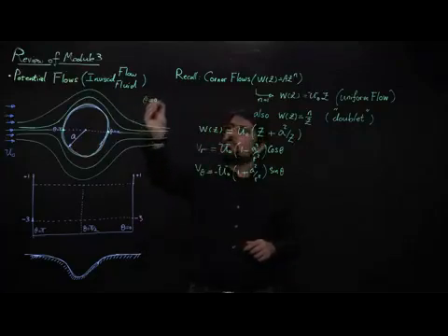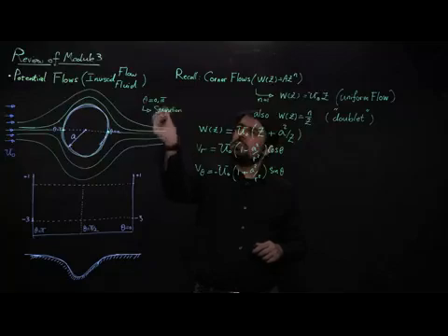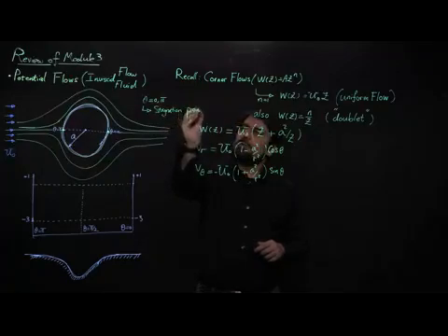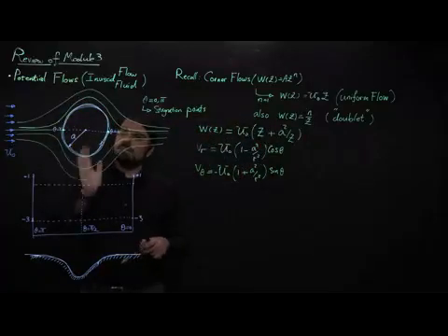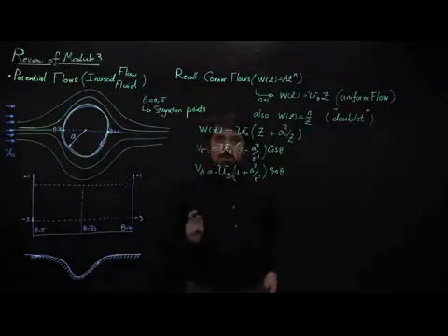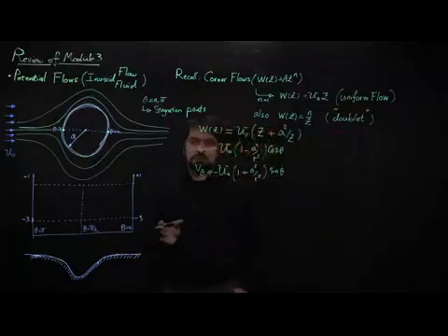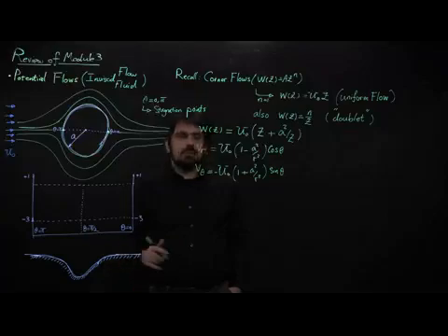So theta equal to 0 or pi are the two stagnation points that we have in this flow, and they are sitting in the front and back of the object in a symmetric manner. The flow has a symmetry from top to bottom, and it also has symmetry from front to back. And in all these potential flow problems, once we find the correct combination of complex potential functions that give us the shape of the object, the rest is just doing some mathematical manipulations and steps. We can calculate the velocity components.